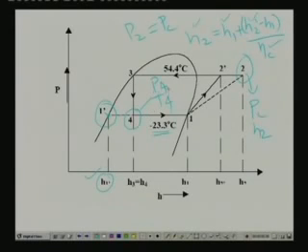So, you have to specify any one and another property. What is that other property? That property is enthalpy, because we know that this process is a throttling process. So, for this process H3 is equal to H4. H3 is known to us, that means H4 is also known to us. That means at this point we know the pressure PE and we know the enthalpy H4. So, from these two properties you can find out the rest of the properties like entropy, specific volume and all that.